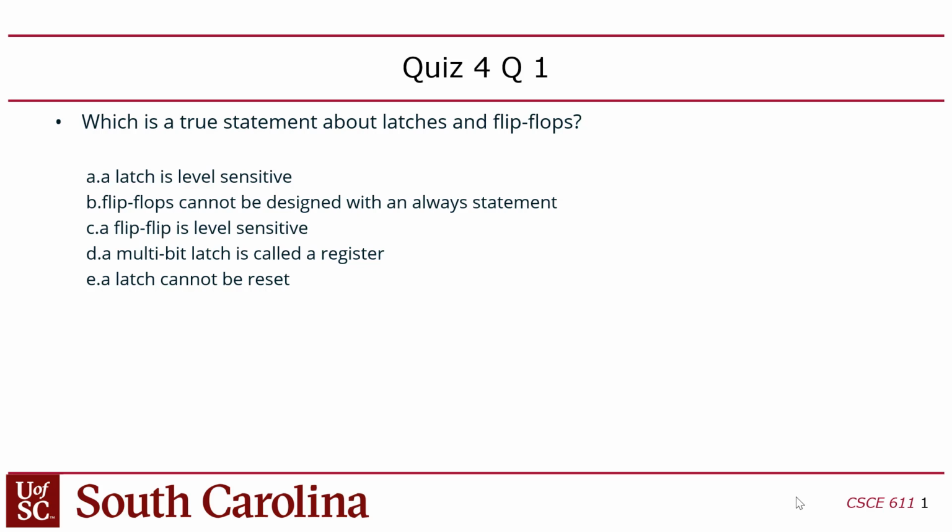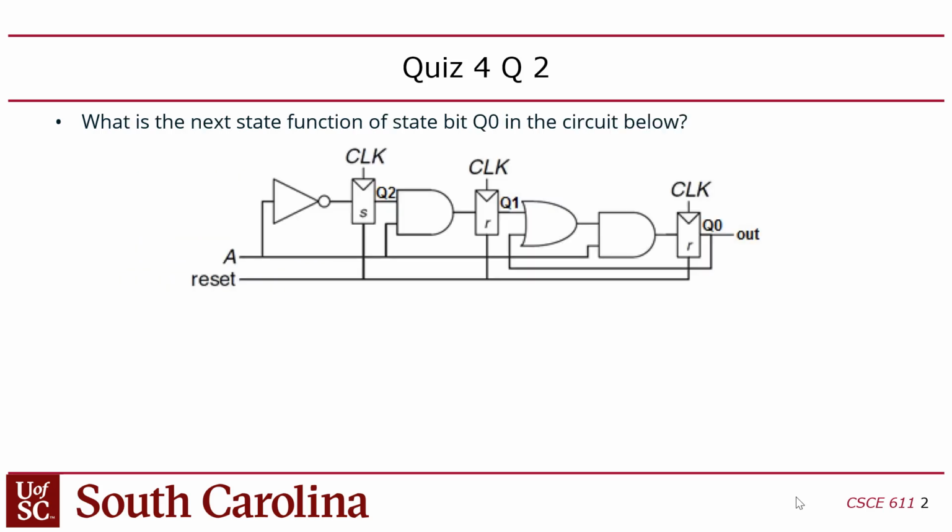That's a little confusing, but flip-flops can only be designed with an always statement, so that's not true. Flip-flop is level sensitive, not true. Multi-bit latch is called a register, that is not true. Multi-bit flip-flop is called a register. And a latch cannot be reset, not true. So the answer is a latch is level sensitive.